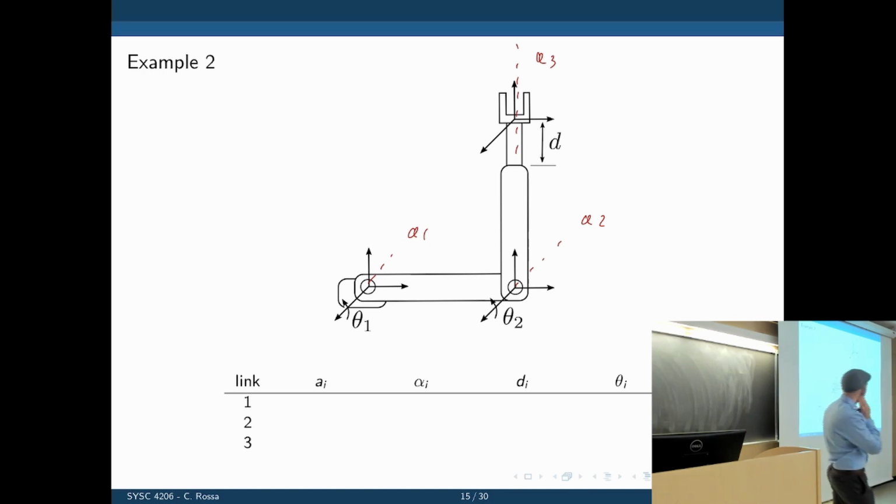But that one also you have to represent in 3D, or no, this one is just going up and down, just the new y-axis. Yes. So with A1 and A2, we can define our Zs. How many frames do we need to fully describe this? We need 1 on the base. We need 1 for the tip here. And another one for the translation.